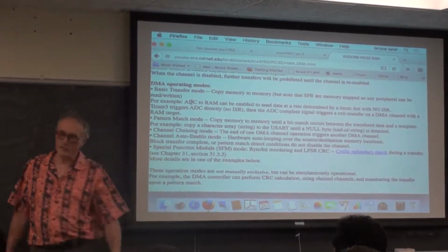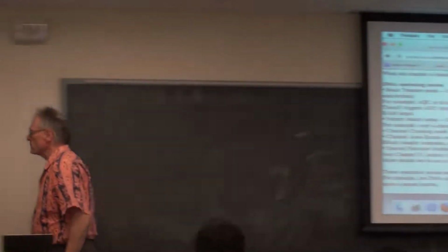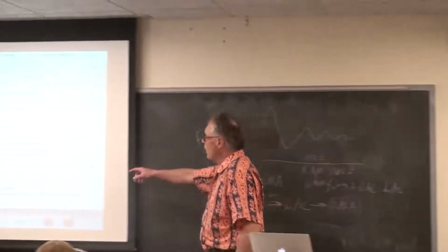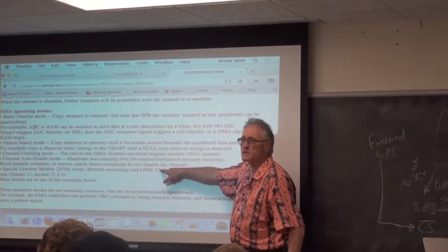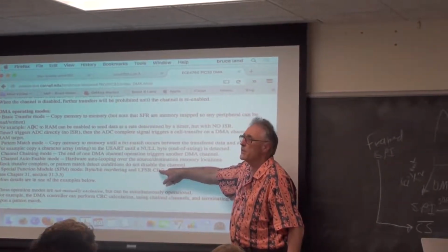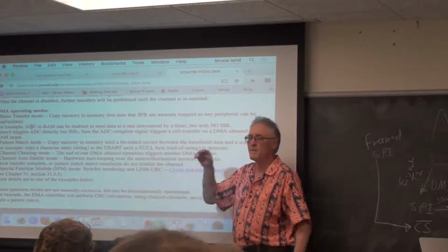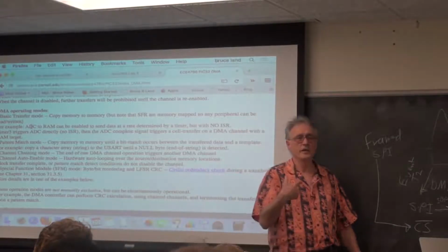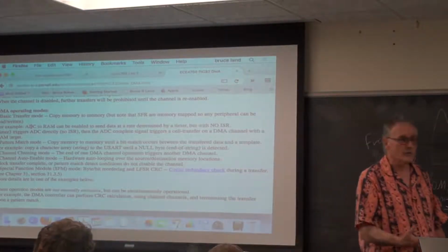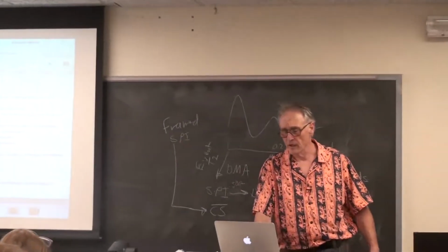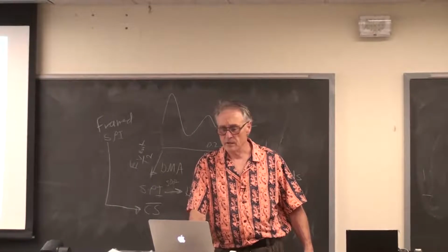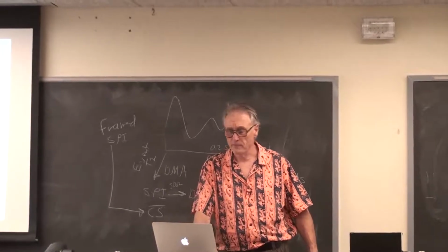There's also a special function module. On our CPU, there is a hardware linear feedback shift register CRC generator that will operate on a DMA channel and do the CRC extraction on the fly for doing cyclic redundancy checks. We're not going to use that.